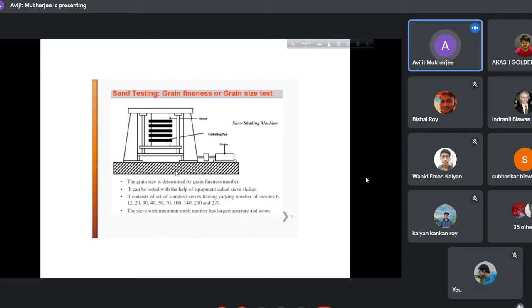So that's why we are starting with the testing of grain fineness number. This porosity or voidness or openness can be achieved by various sizes, as we have mentioned, size and shape. In considering this test, we don't consider the shapes, that is geometrical shape may be anything, but sizes are considered here. Now, this grain fineness test gives you a concept of GFN, grain fineness number.